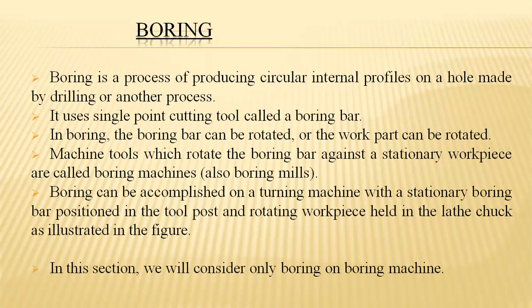In this, the operation can be carried out in two ways. The first is by rotating the boring bar, we can progress the boring activity, enlarging the already made holes produced by the drilling process, or smoothing the rough profile of the internal hollow sections.